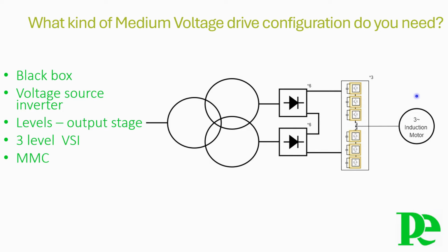Medium voltage levels are obtained by adding together the outputs of multiple power cells. We can state that this drive delivers a superior sine wave output voltage and current, thereby eliminating harmonic heating and insulation stress on the motor, and reducing significantly the torque pulsations to levels lower than 1%.